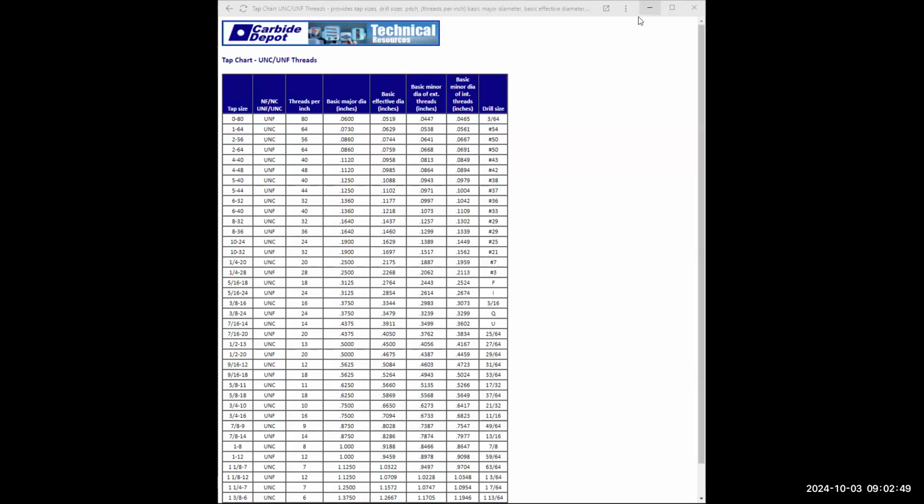All right, so we have all the holes so far. Now we have to do this one, which is a little tricky here. It's a little tricky because it is a countersink hole. And it says that the angle with the countersink hole is 82 degrees. Now, what that means is we have to change the angle of our cursor.